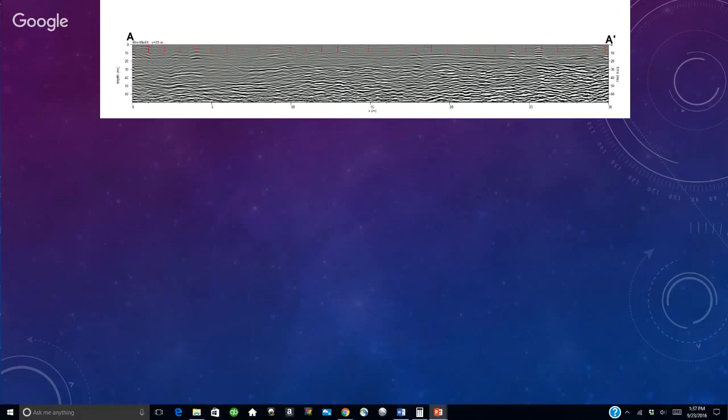Of course you can. And here are those possibilities. Those are generally the buried hyperbola. Some may be metal. Some look like they may not be metal. Those over here, for example, with the multiples, appear to be metal. And those over here appear to not be metal. Now, whether or not they're actually pipes or some buried utility is unclear at the moment. But there are definitely some candidates for possible utilities in this location.